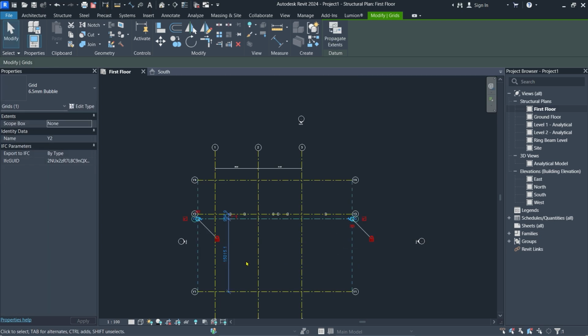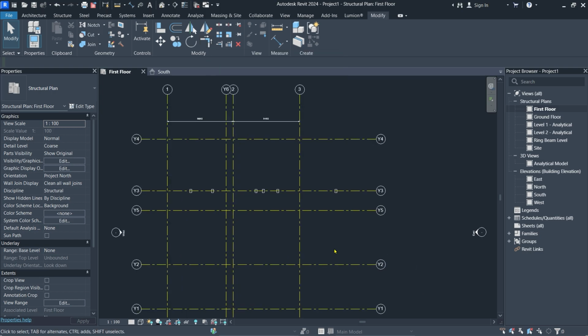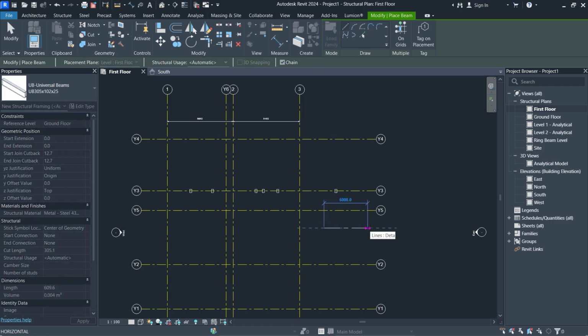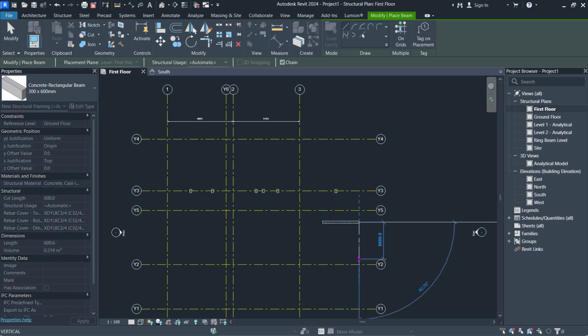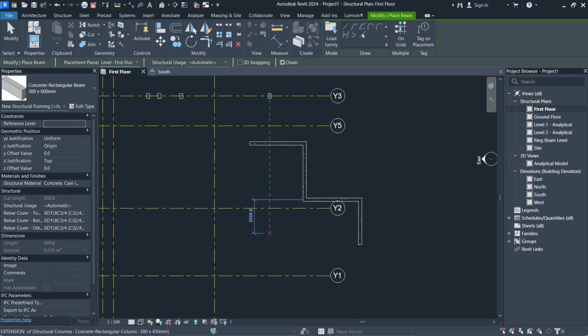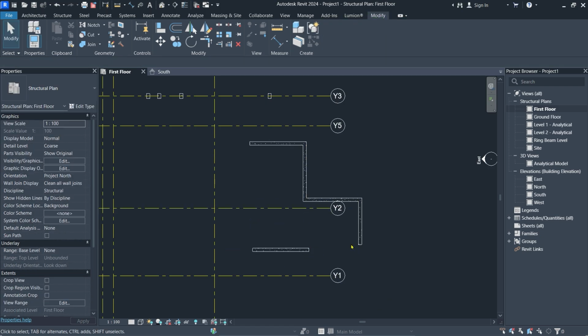As simple as that. However, before I leave, I want to point out one, which is trim and extend. So trim and extend, if I have, let me say, a beam. Sorry, I'm not going to illustrate how to draw these beams in this tutorial. I have a separate tutorial for that. Let me say I have my beams like that, and there is another one here, and I want to join this to this. What I do is use this tool.